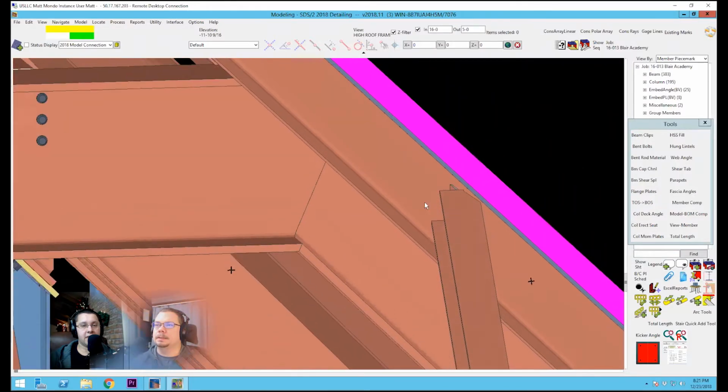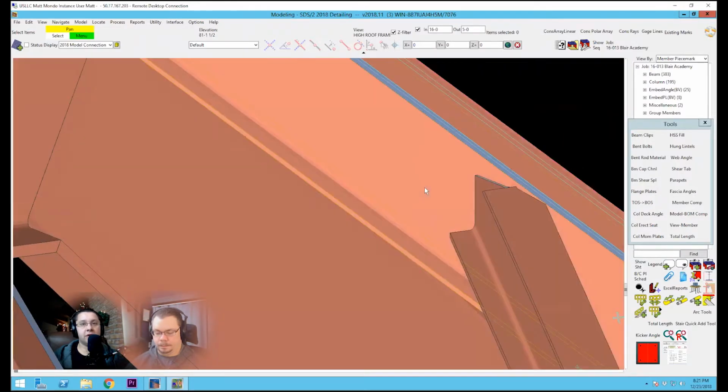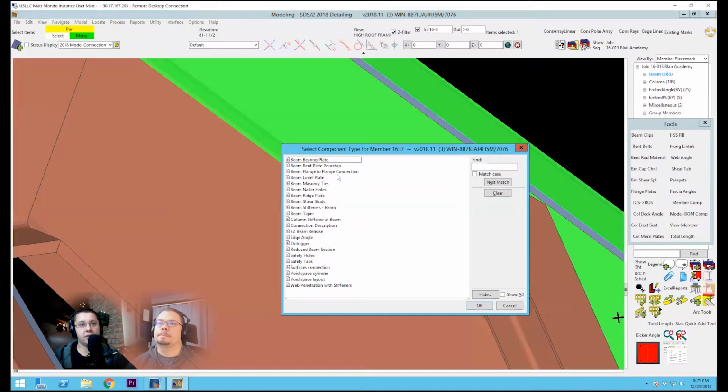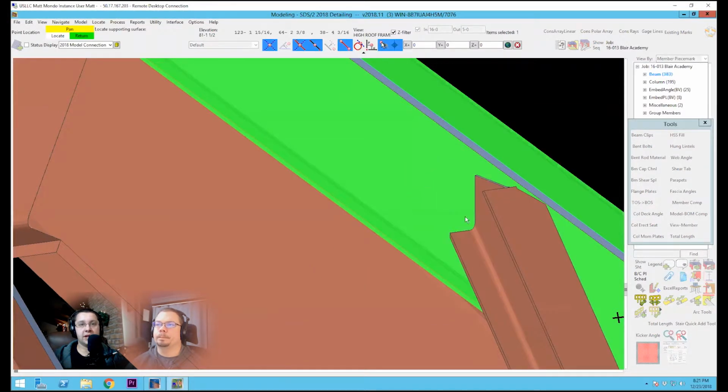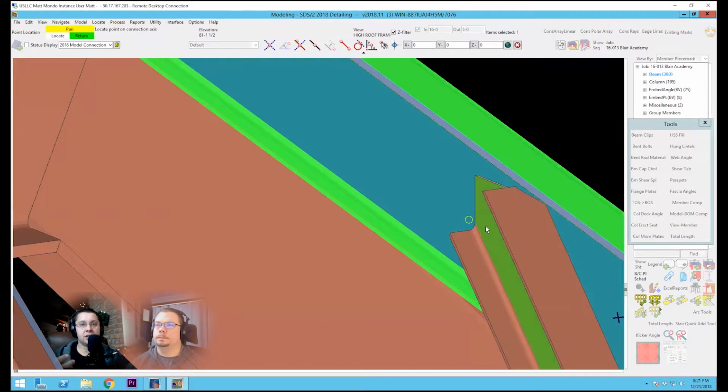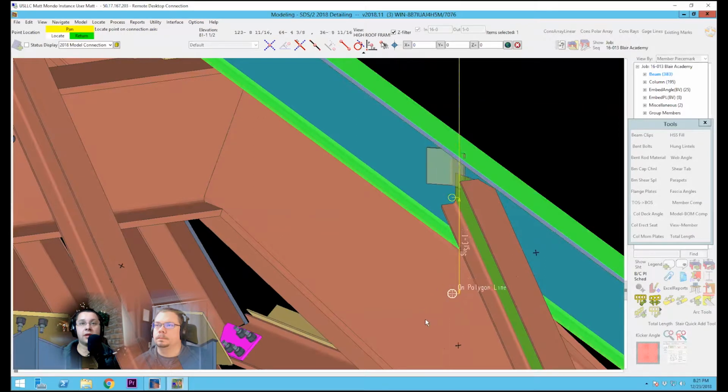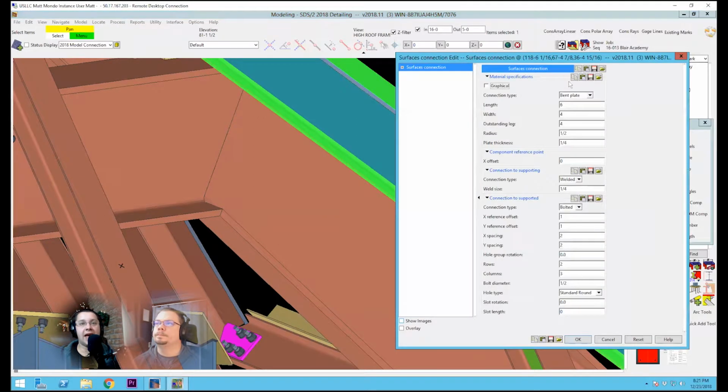Yeah. And if there's some of you modelers out there, maybe you're junior, maybe you're senior, and you're just overthinking it, but the important part with these hip and valley connections is to make sure that you get a connection and that it all kind of fits on there. You don't have to worry, is it down 3 inches exactly? Is it down 5.5 for a nice round number? Get it in there, get a correct connection that all fits together. And on these hip and valley jobs, that's good enough.